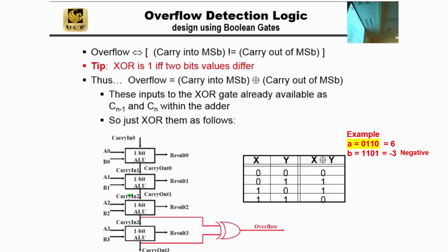So what is this number in decimal? 6. And what about this? But careful, because it's 2's complement, is this a positive or negative number? Negative. It's a negative number. So one way to do this is to invert all the bits and add 1, which gives 3.